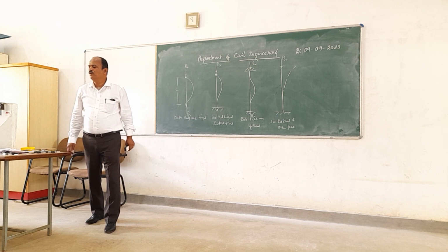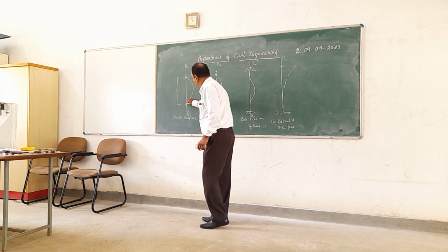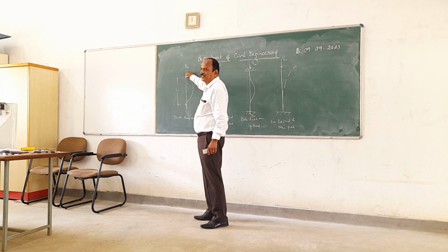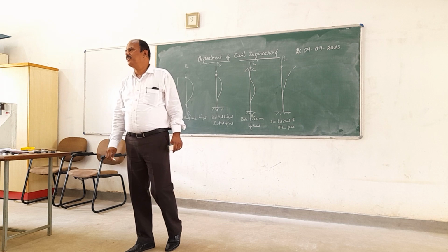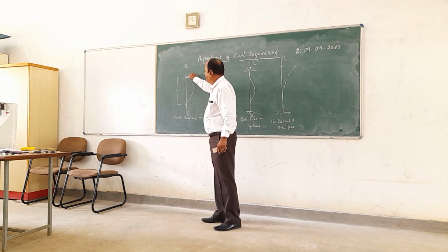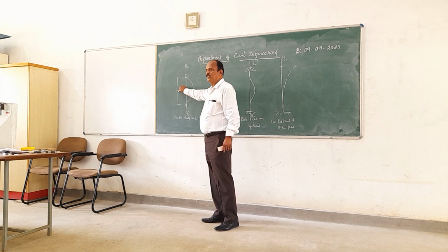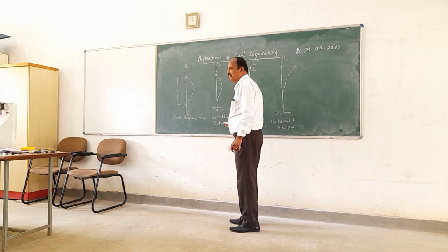Okay. Now, when you observe this nature of bending, these two end points are hinged. What is the moment carried by those hinges? Always it will be equal to 0. It does not carry any moment. Is that right? Now, these two ends are hinged. L corresponds to the actual length.